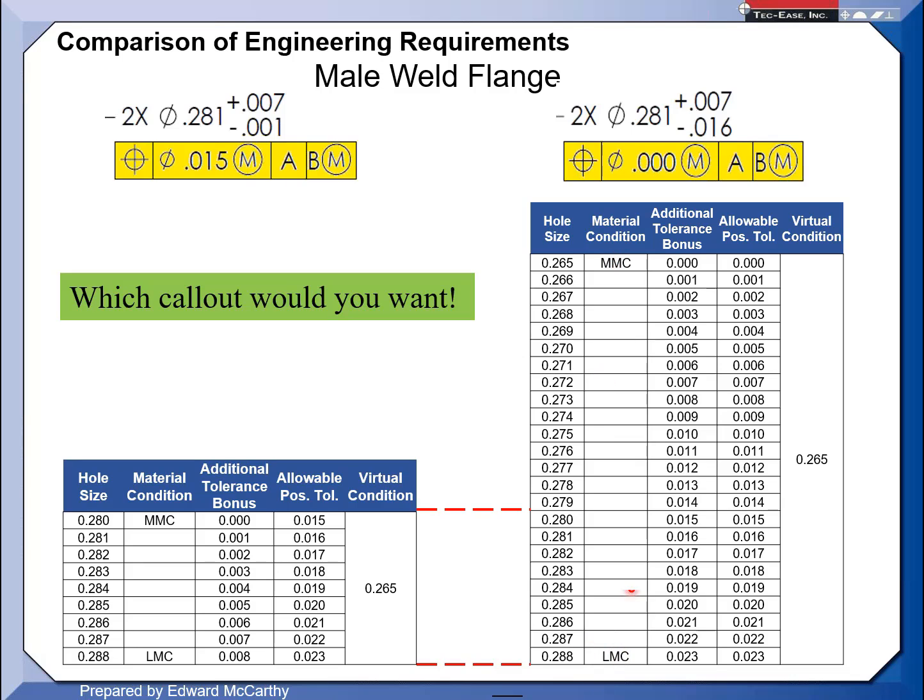So again, hopefully my manufacturing engineers are looking at this and making a decision based on process. I've had equipment where the machines were brand new, and they might run it down near the MMC size so that if there are any issues, they can blow the hole open bigger. They might have a variety of different machines available, so based on the probability of being compliant, they pick the appropriate tool size to make sure they don't violate either of the limits.